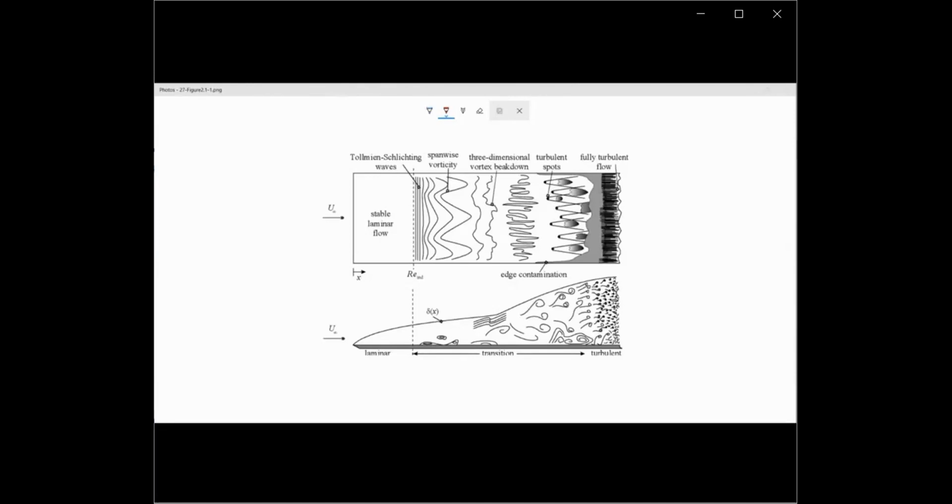For the integral boundary layer method, if there's a pressure gradient, how do you apply it? Basically, you assume a different velocity profile instead of a power law, and that's called the Pohlhausen solution. We are not going to go into that, but until this point, you have learned many fundamental concepts related to boundary layers. So I tried to make a short summary of it.